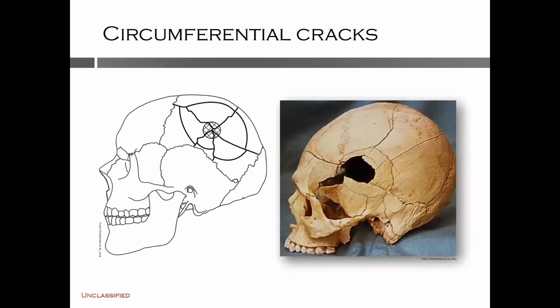If a structure is continually loaded, the radially fractured segments can bend inward, causing circumferential secondary cracking. This appears as roughly circular, semicircular, or arc-shaped cracks that are offset by the radial cracks, which came first. In these figures, you can see the initial radial cracks from the impact site and the arc-shaped cracks on the segments.